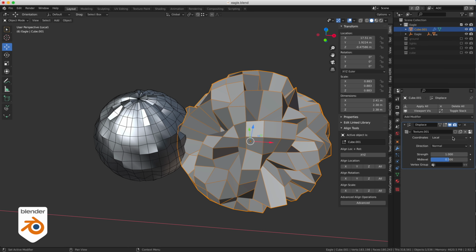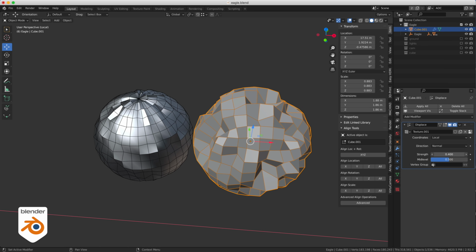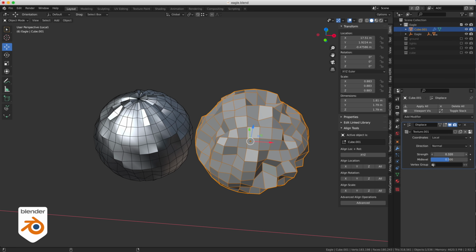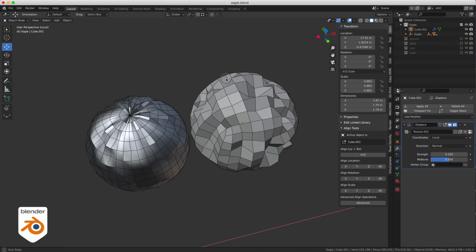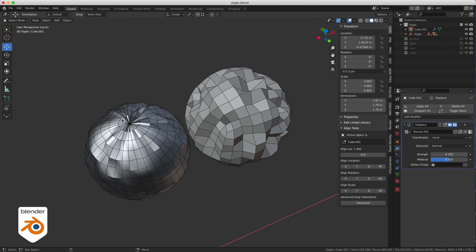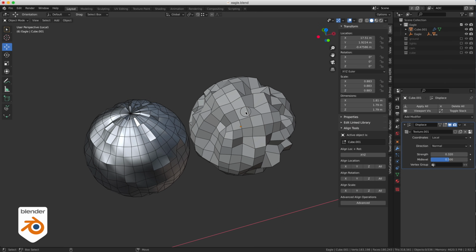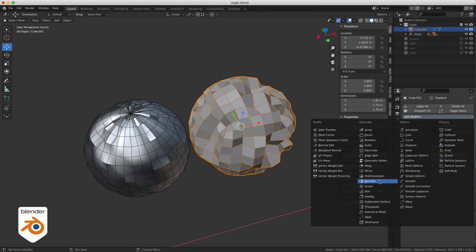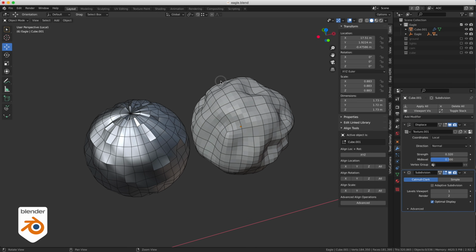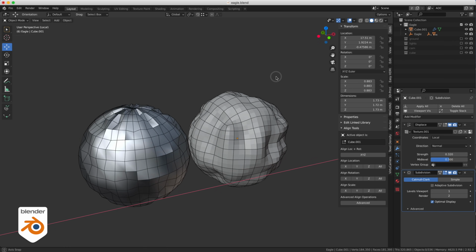You see the little 2 button here? If I click on it, it's going to make it an independent texture, so it's not going to affect the other one. Now I can modify it without affecting the first sphere. Okay, now you can already see the difference. This one here has a pole and doesn't look very good. Let's subdivide this one a little bit more so we get a better idea of what it can look like. And then I need to maybe smooth shade it.